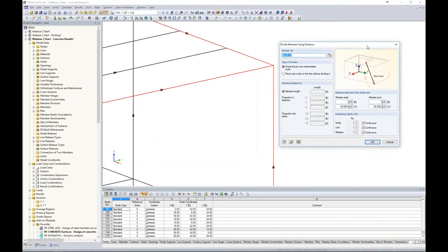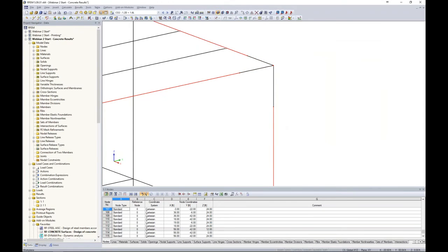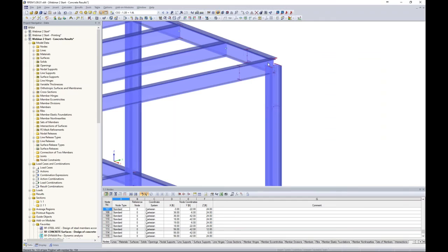Now, because I switched around the member orientation, the member ends are all located at this particular node, so 3 feet from the member end is where I'm going to divide it. Now, I've done nothing more but just create smaller members out of my initial member length. Now, if I render this, sure, we get this rendered view of our W section, but turning it back into